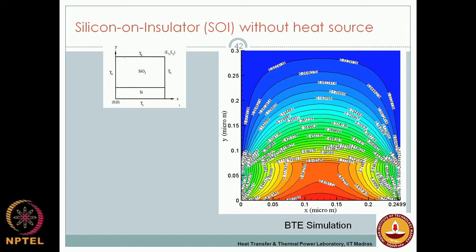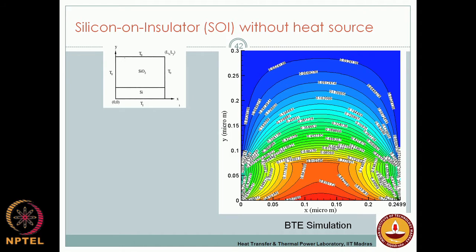We have a system where you have a silicon film which is deposited, on top of the silicon dioxide which is a dielectric. Usually this is the substrate. The typical semiconductor device, what I call SOI, silicon on insulator. So, the SiO2 here is the insulating substrate over which you have silicon, which has a very good thermal conductivity, whereas SiO2 has a very poor thermal conductivity here, and we just try to solve a simple heat diffusion problem